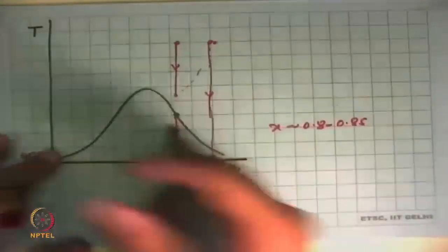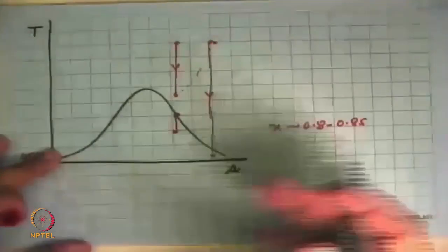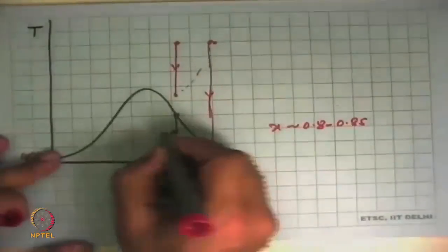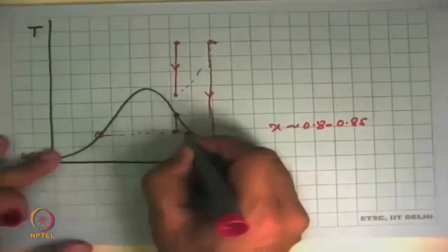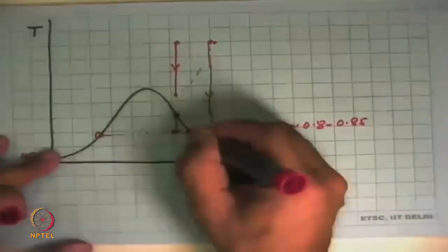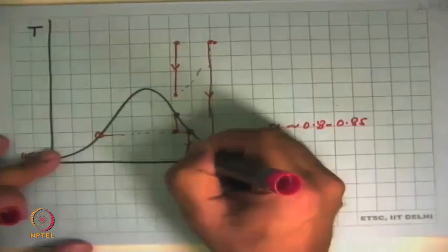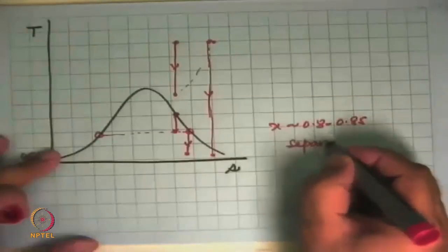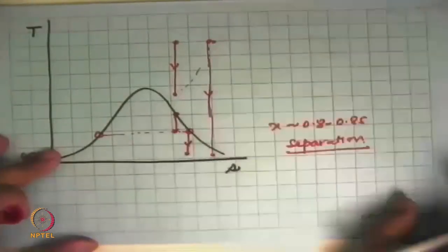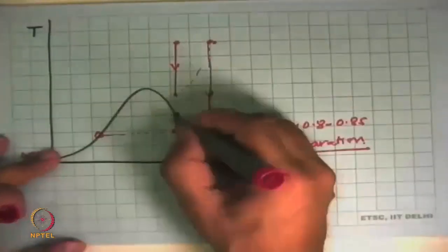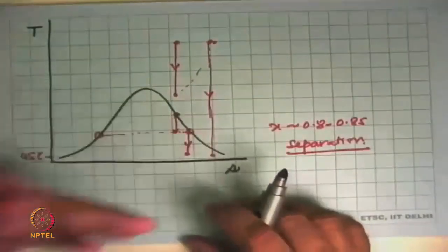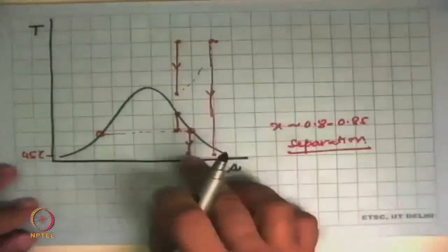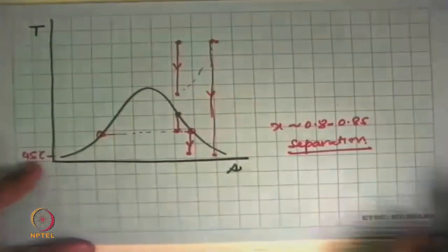So what we'll do is take this steam out and physically separate the liquid from the vapor because there's a big density difference. The vapor, when it is separated from here, will come over here. The liquid will come over there, and then we put the vapor into another turbine and expand it until the cooling temperature is reached. So this is a physical separation device. We will look at this later on when we look at another type of application. But that's what happens in nuclear turbines, including nuclear turbines on ships and submarines. We are always dealing with a wet substance, and you have to always be very wary about it.